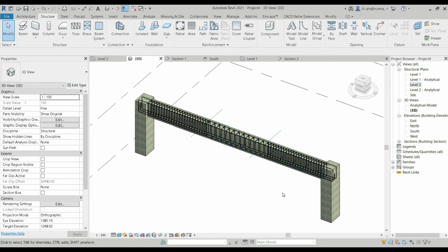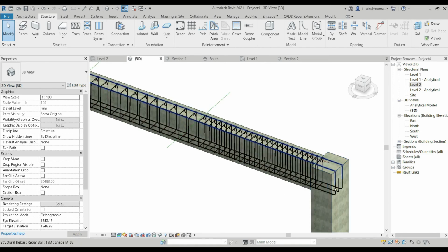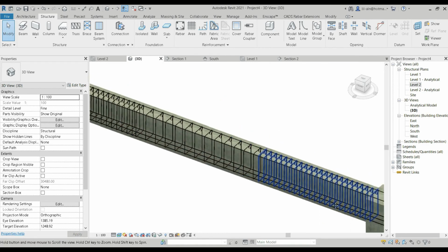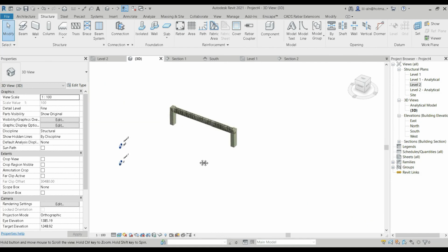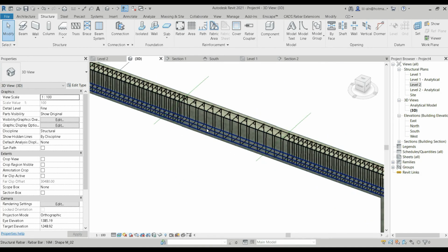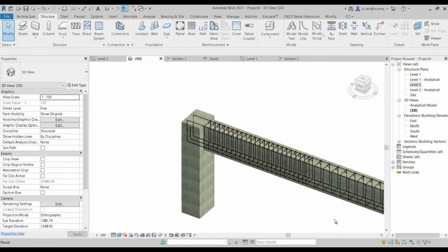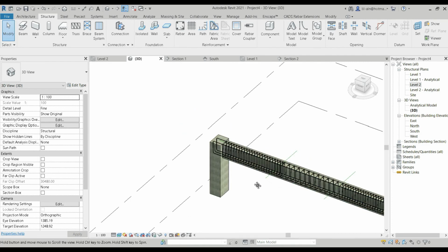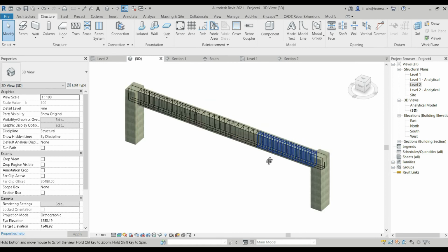So now the cover is done, the beam is done, the compression and the tension reinforcement is done, the stirrups are done, and the stirrups towards the columns have a less center to center spacing, while the stirrups in the middle have more, because shear force towards the columns is the highest, and these are called shear reinforcement for a reason. So I hope you get my point.